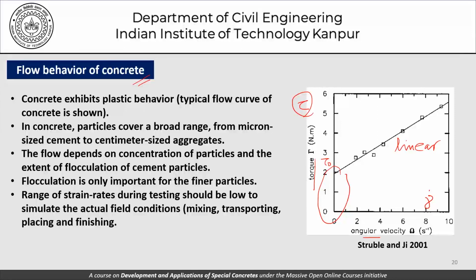So concrete shows plastic behavior. Typical flow curve is shown. In concrete, particles cover a broad range. We know that, from micron-sized cement particles to centimeter-sized aggregates, and the flow characteristics depend on the concentration of particles and the extent of flocculation of cement particles.